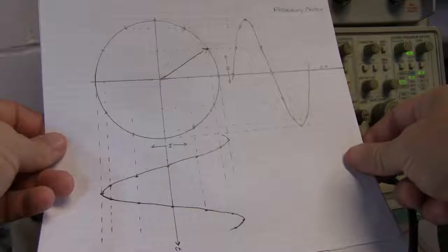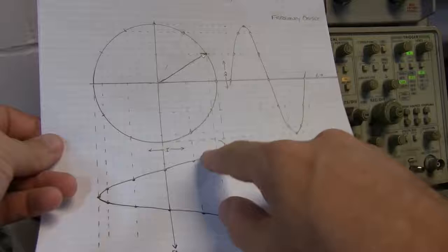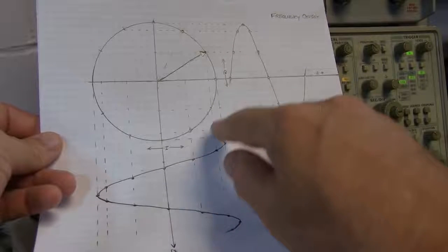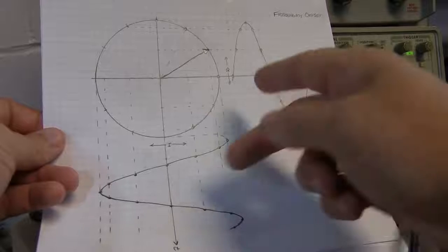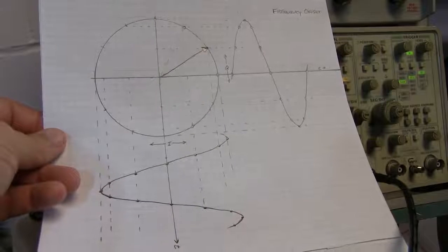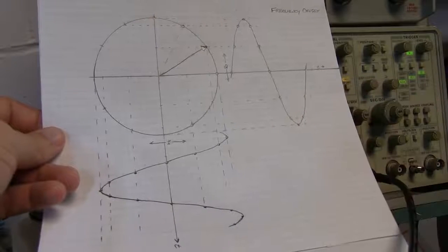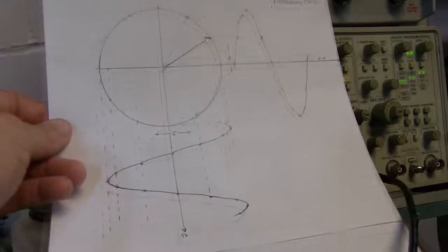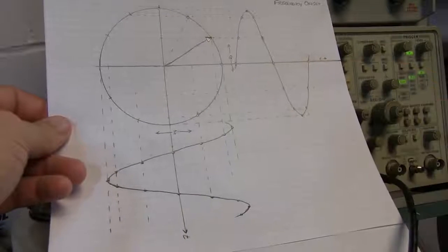would represent if you looked at it in the time domain is that, in one case the Q signal is going to be leading the I, and in the other case the I signal is going to be leading the Q. So by essentially reversing that situation, we can, when we modulate a signal, create a positive or negative frequency offset. So one way to think about that is if I have a pair of sinusoids in quadrature,